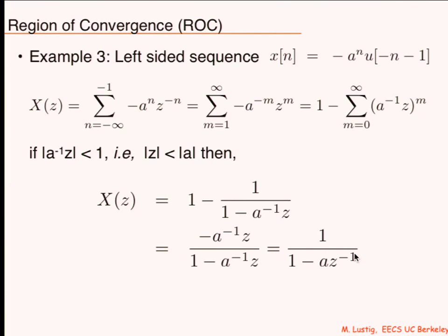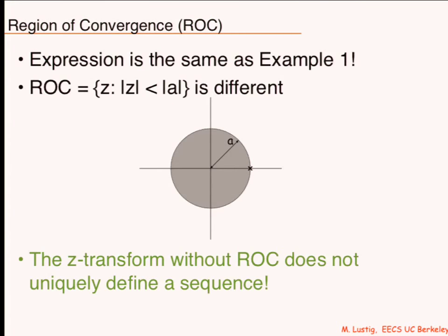Beautiful exam question. For example, here's a z-transform, compute the inverse. Then you're like, oh yeah, I'll do this. And then most of you are going to come up with the right-handed sequence. I bet maybe one out of a million is going to pick up the left-handed sequence. But then all of you are going to be wrong unless you say it could be both, because you didn't define a region of convergence.